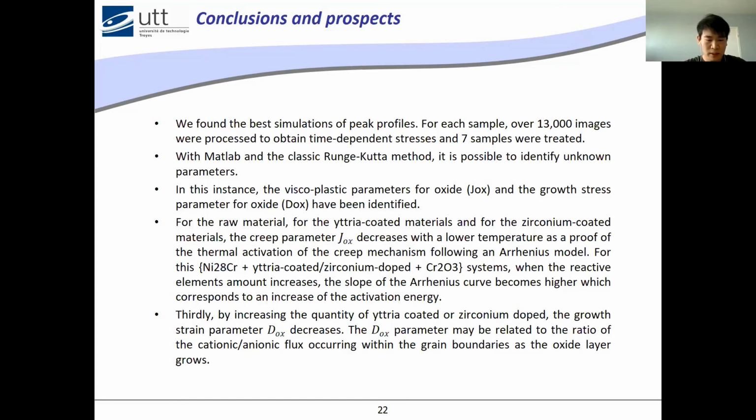And thirdly, by increasing the quantity of yttria-coated or zirconium-doped, the growth stress parameter Dox decreases. The Dox parameter may be related to the ratio of cationic and anionic flow occurring along the grain boundaries as the oxide layer grows.